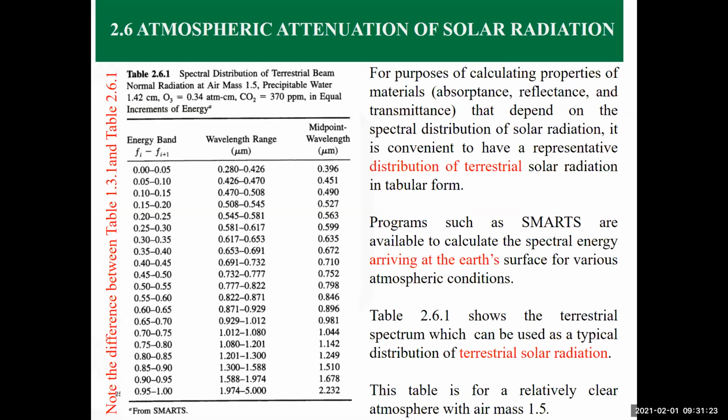The other component is reflection, which is for shiny surfaces that you don't need to heat, but you need them to focus the energy on a neighboring surface. Some parabolic trough collectors are of that type, so that the energy falls onto the surface and is reflected into a tube that has a fluid inside to be heated. So this is an example of using reflection.